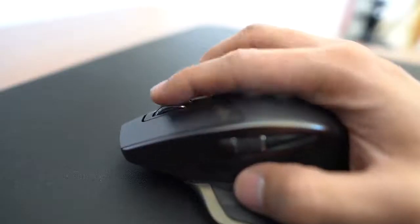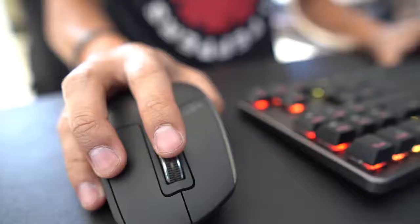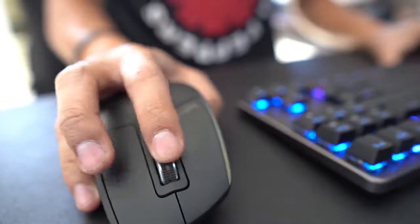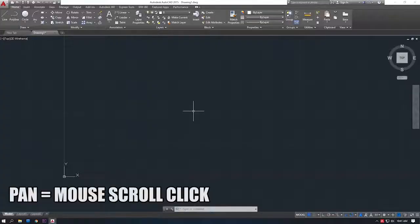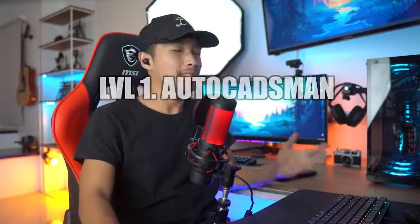Anyways, before we learn how to make lines, let us first learn how to navigate our drawing sheet. To zoom in and out, you just need to use your mouse scroll wheel. That's simple. Then to move our sheet around, you can just click down on your mouse scroll wheel and that will activate the pan function, which lets you drag your drawing area around, like so. And boom, you just leveled up. You are now a level 1 draftsman. Or let's just call it AutoCADsman, because that just sounds cooler, kind of like a huntsman, but with AutoCAD.